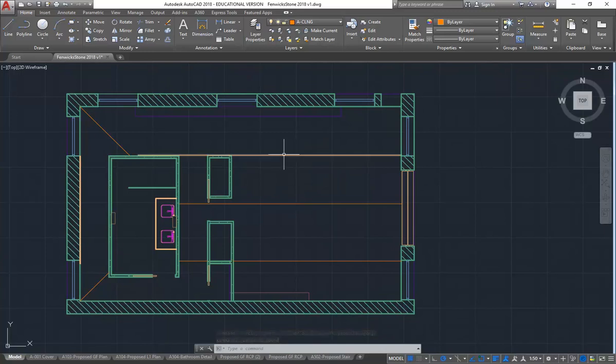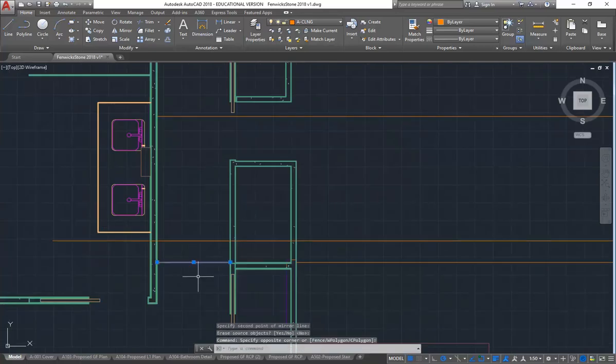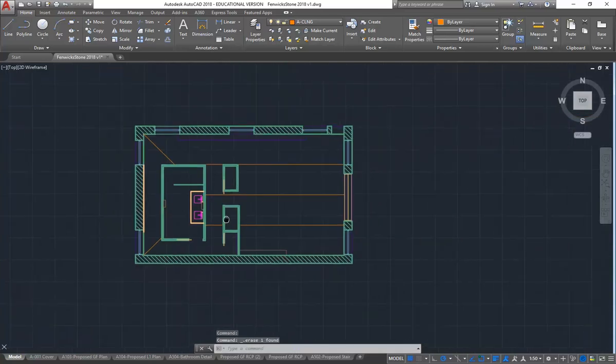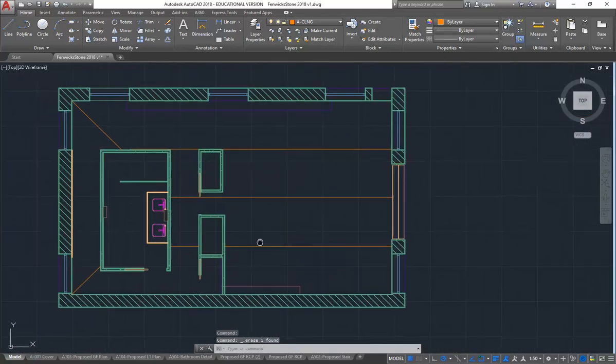Yeah, so what's happened there, this one's not symmetrical, so I must have again mirrored using the wrong line. So I'll just mirror again this line using the correct one that I've now drawn in. That's better. And just to save time, I'll move these up, and then I can delete my new line. There we are. So that should be symmetrical now.